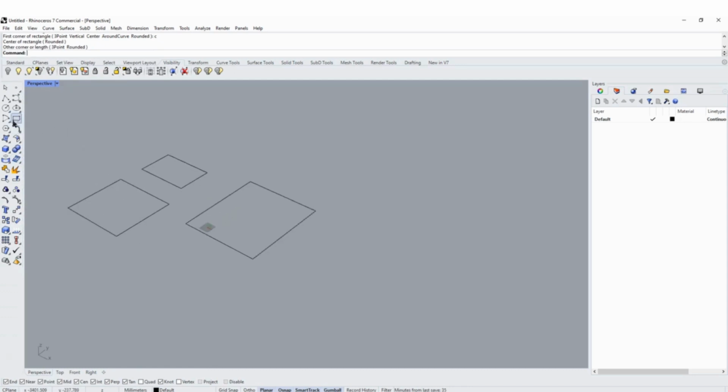So let's say that I want to do a specific rectangle that is starting from the point 0 of the drawing. Honestly, ground zero of the drawing, let's start there. So I can say that I want my first point to be at 0. Type in 0, enter, I'm starting right over here. And I want it to be in total 100 millimeters by 100 millimeters.